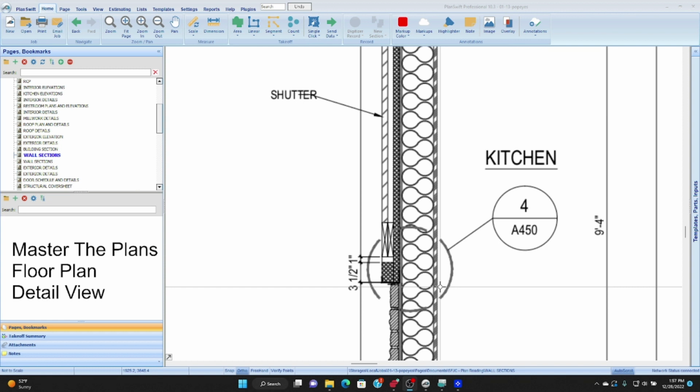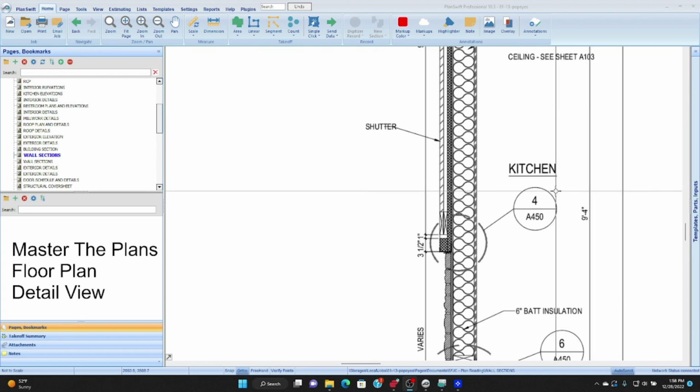And the architect will point us to different pictures using different symbols. It looks a lot like the section view marker, only in that it's a circle. But the architect can't sit next to us when we're doing the construction, telling us what to do and making sure it's proper. So they lead us by pictures and symbols to other pages that give us more and more detail. So the detail call out, if we watch the views video, is the last of the construction views that will give us the most detail.